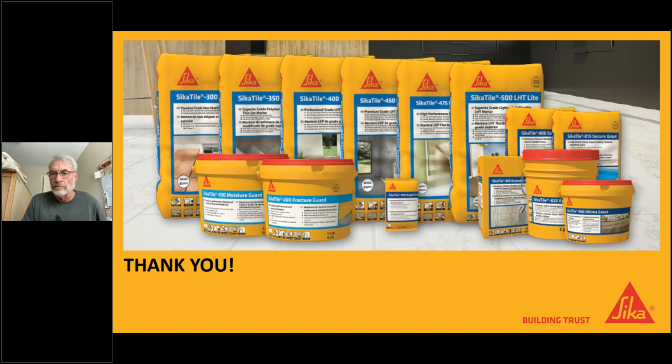If you're getting the coverage, I guess here's the way that I would look at it. That's actually a great stumper of a question, but I've got to think about it for a moment. I would be using a white epoxy. We manufacture an epoxy grout that is not only a grout, but it is also a mortar. I would choose a white color. I would make sure that I'm getting complete coverage on the back of it so that we're not seeing through those light marbles. As we all know, the white Carraras can be a little translucent in color.